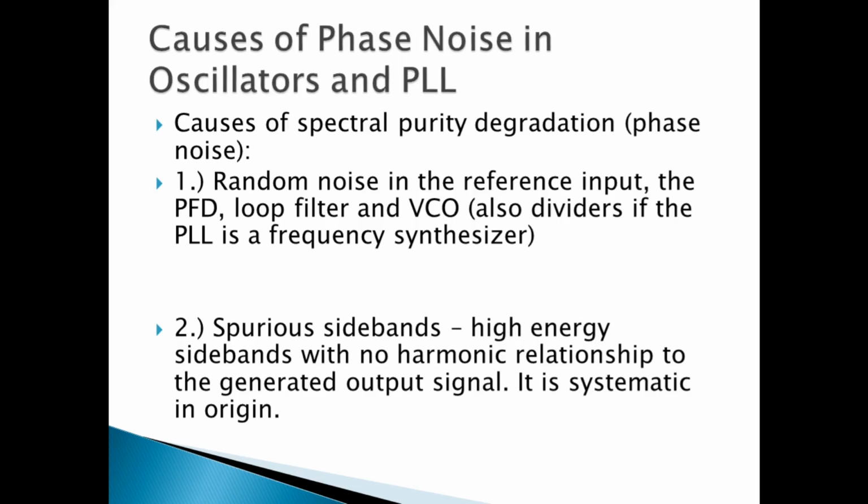So, for example, in a PLL, you have the phase detector, the loop filter, the VCO, then there are various other elements in a VCO, the tank circuit. Now, all of these elements will be responsible for their inherent noise, which gets into the entire system and degrades the performance.